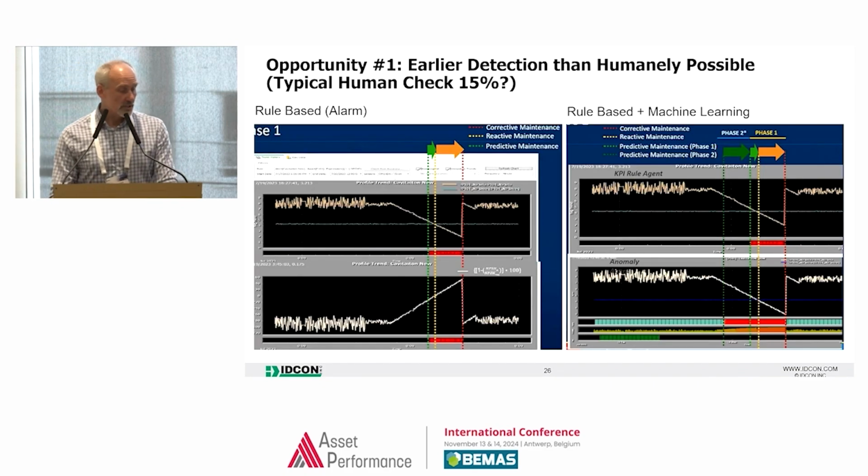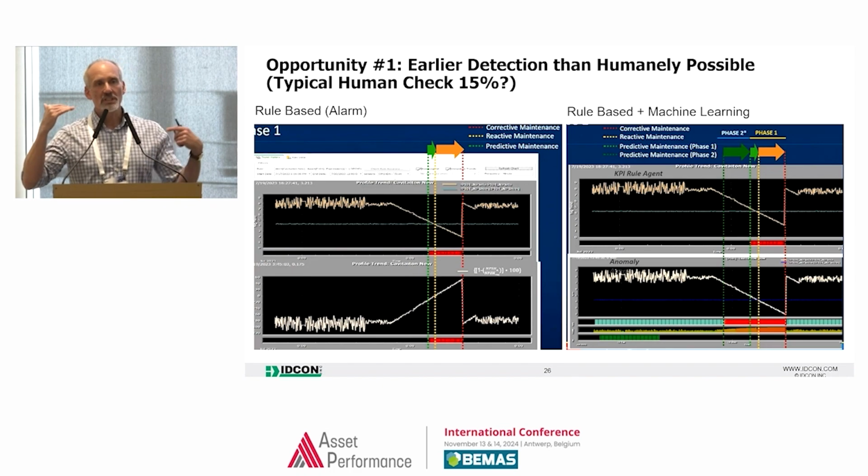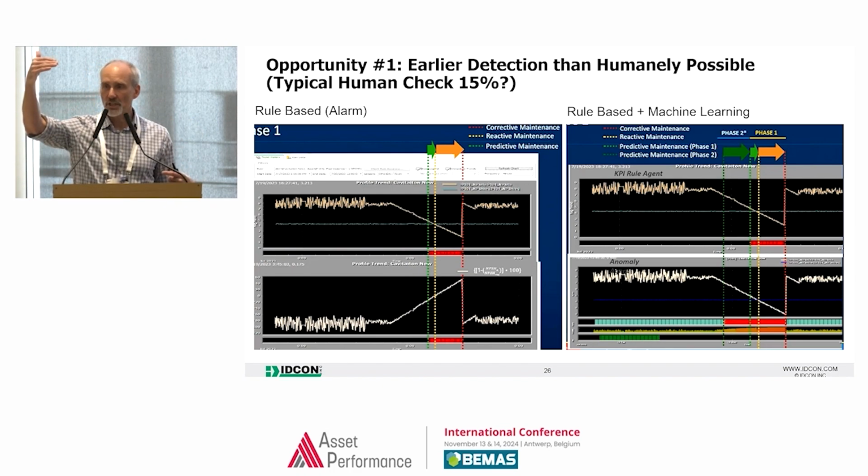Some cool stuff we can do is we can supposedly find failures earlier with these sensors. By AI and learning, we can find failures earlier. We have seen that with some of the vibration data that we have. This happens to be Aspen Tech, and we look at net positive suction head, right? NPSH. And we looked at that as a percentage, and we start seeing that changing, that basically the pressure is changing. So we see that over time, and we can now catch the failure earlier.